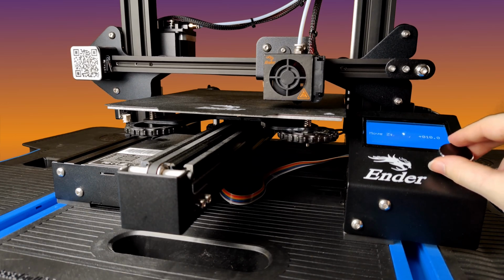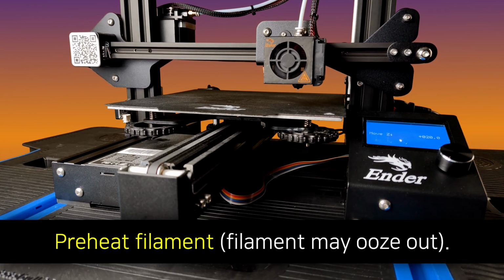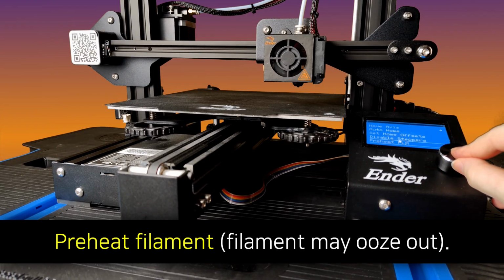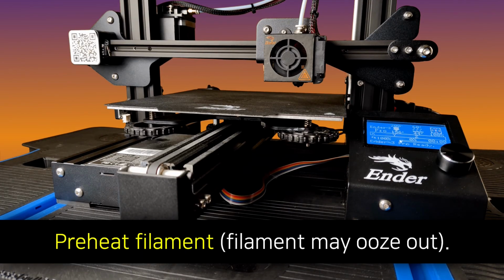After that, I moved the printer head up on the Z-axis, and then I started preheating for PLA filament. PLA plastic is a common printer filament. If you're using a different material such as ABS plastic, then you'll need to preheat with a different temperature. If the printer has been used before, some filament will likely come out when preheating. This is why I moved the nozzle up so that it's easier to grab the filament that oozed out.